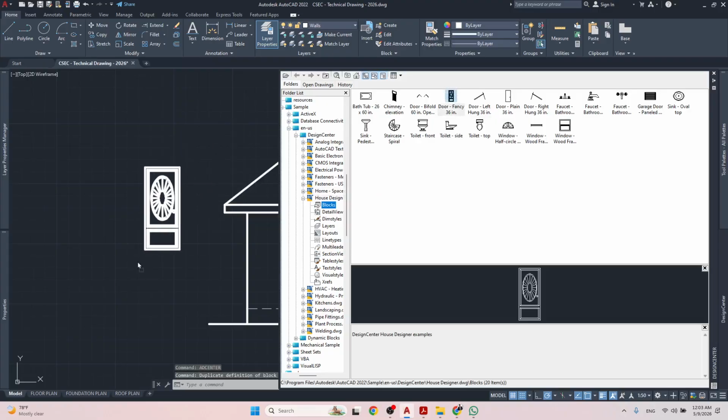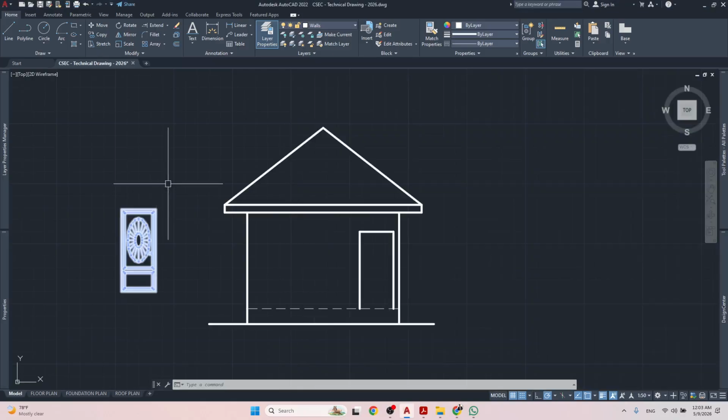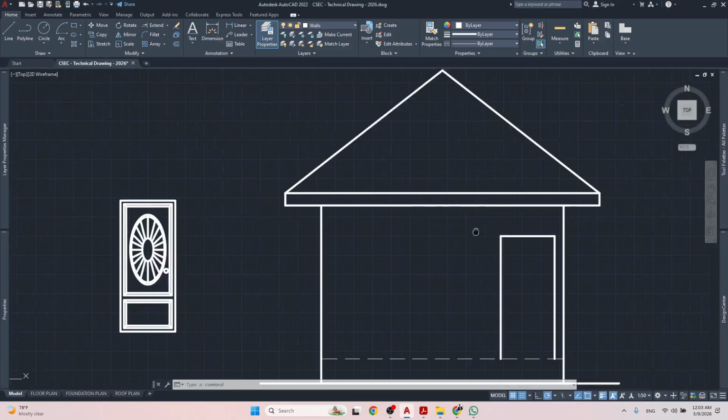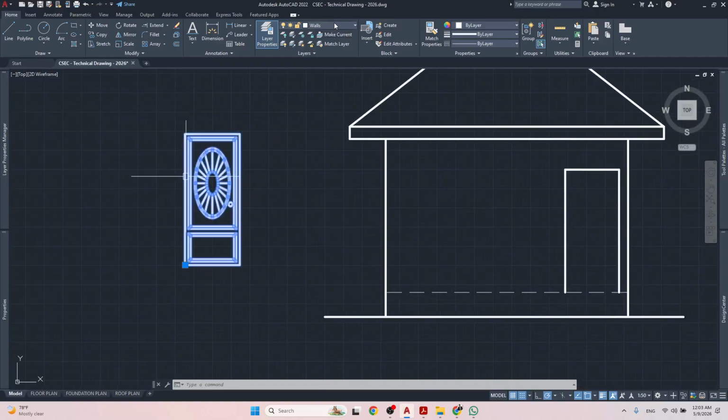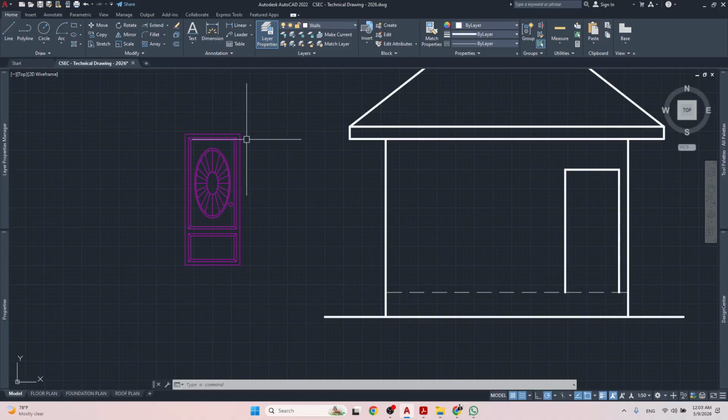So I have some fancy doors here. I can pull this out. This space is 2000 millimeters high by 900 millimeters wide. Is my door the same thing? Let me put this on the correct layer so I can measure this. So this is 914 by 2131. So what I'm going to do is rescale this from 914 to the width of this opening, 900.